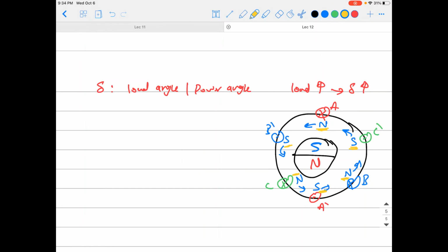induced voltage comes in the stator and the current moving in the stator winding because it's connected to a load. So this current moving into the stator winding will also produce magnetic poles. And the way all the machine works is that the magnetic poles of the stator are coupled with the magnetic poles of the rotor. Each north pole of the stator will be coupled to a south pole in the rotor and vice versa. And because the rotor is rotating in some direction, and these poles of the stator are also moving in some direction, they will be coupled together and rotating together at the same speed, which is the synchronous speed, ns, 120 F/P.